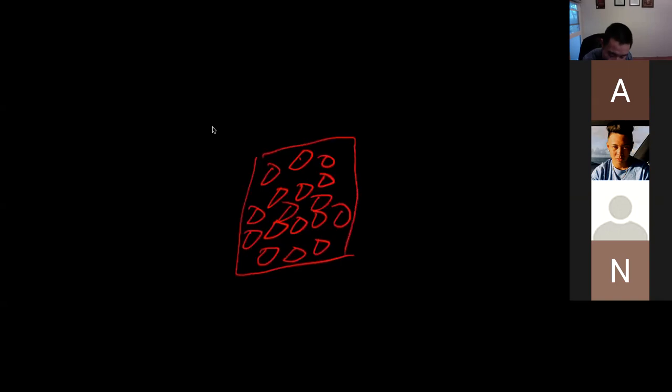So let's say these are cement particles. We mix cement particles with water, and we ignore aggregate here. But when we introduce silica fume, which is much smaller than cement, the silica fume can pack into the spaces between cement particles.